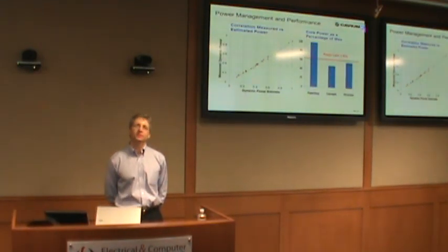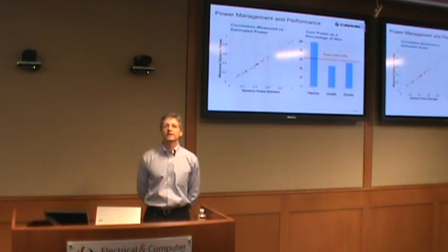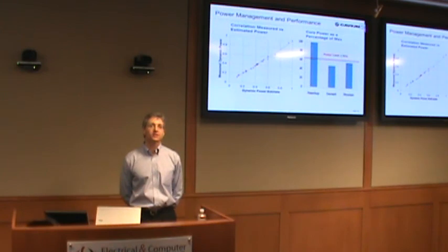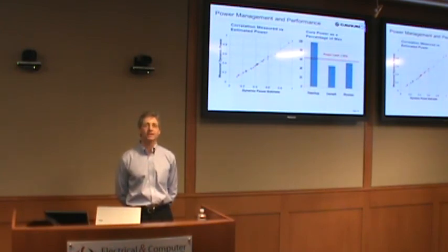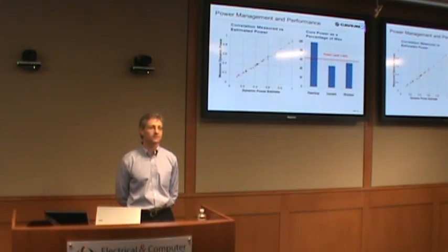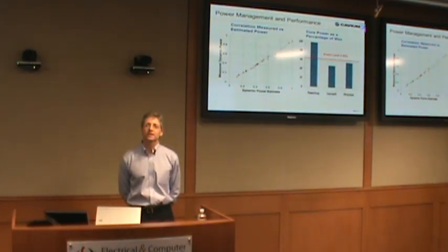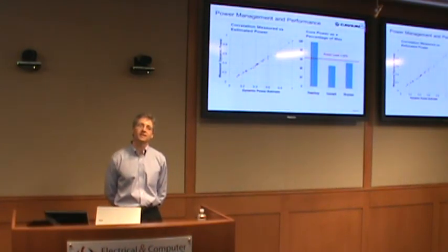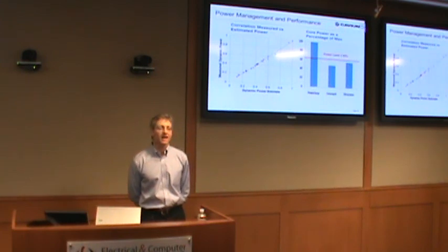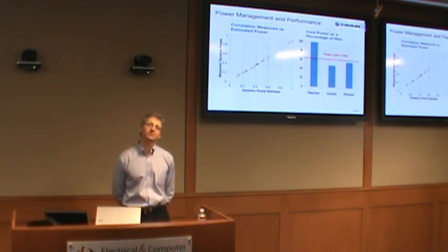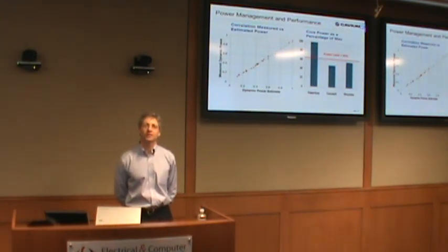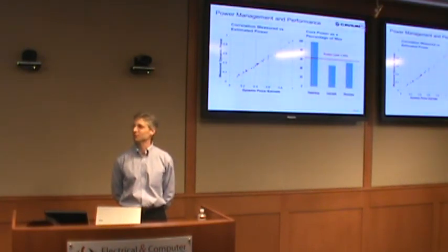So what is that buy-in? Well, there are two interesting aspects of that. One, the left diagram shows it's important that our estimate correlates to the actual consumed dynamic power, and the left graph shows that yes, indeed, for a variety of applications, there's very good correlation. Another interesting thing you can see from this diagram is that for any given application, there are a lot of different power levels from this core. Power goes from like 0.1 on this diagram up to 1, and guess what that one up in the right corner that's 1 and 1 is? That's our friend, the power virus.